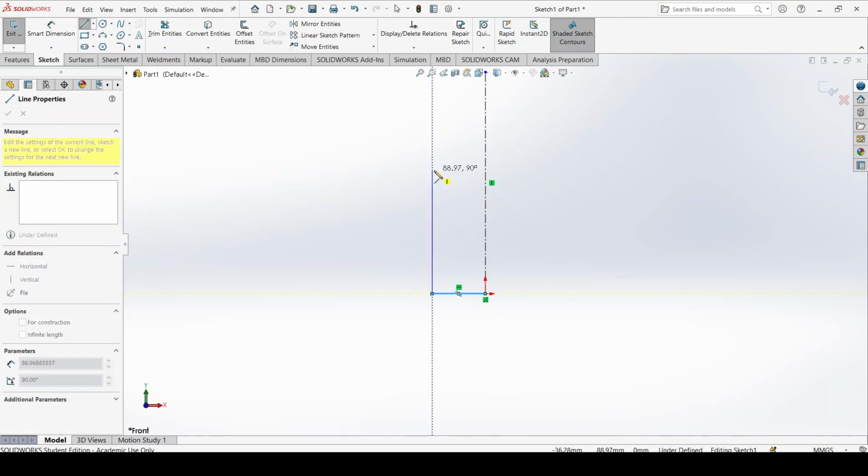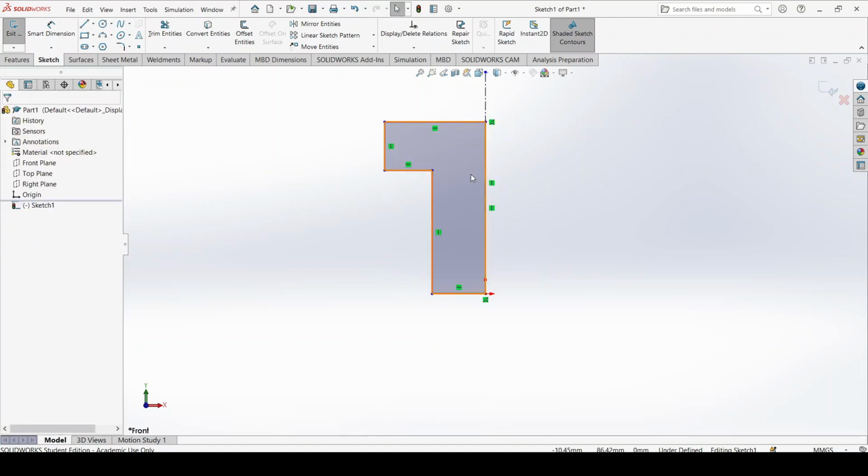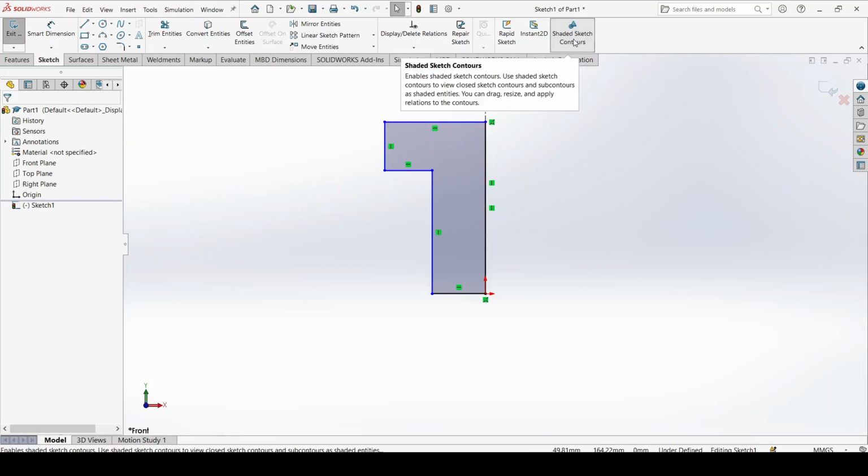1, 2, 3, 4, 5 and 6 lines. We'll close off the contour as well. This is great. And do bear in mind that I'm leaving it as a solid because I want to do this M5 thing afterwards. And this is of course a thread, and we'll do this with another tool called Hole Wizard. But just wait, we'll get there in time.